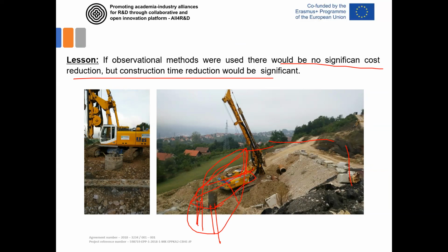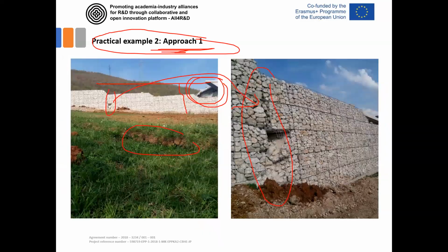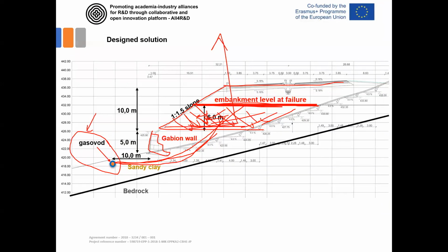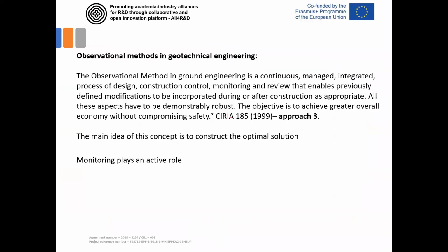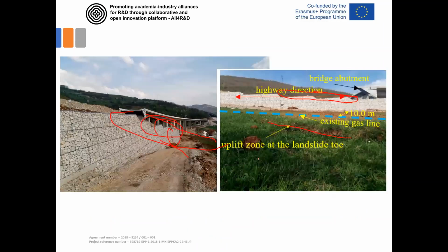if we decided to follow the displacement, to monitor displacement during construction. As soon as we recognized some increment of the displacement prior to this phase, maybe 2 or 3 months before, when the embankment was here, we could introduce maybe some deep piles here and here, to support this sliding, to prevent it, which caused a huge construction time increment and quite a lot of problems for the investor and for the contractor of this route.